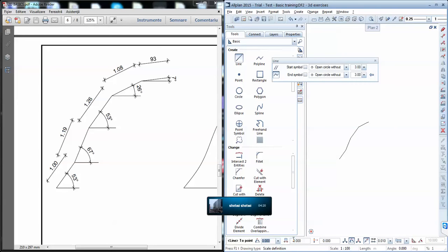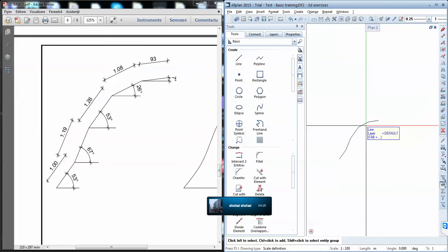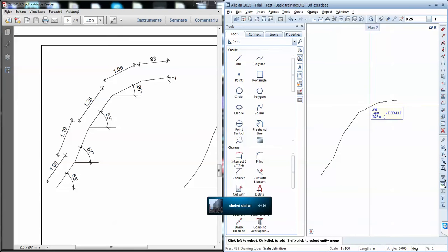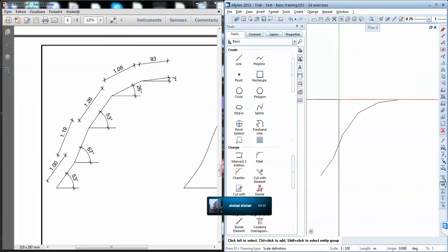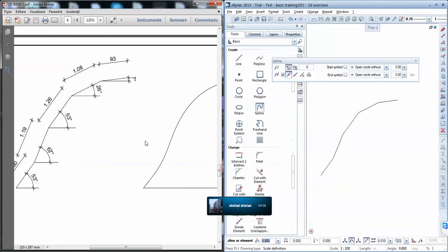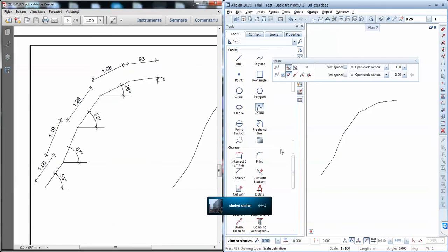And now the last 7 degrees and 0.93. This is the shape made using lines, so it has a lot of corners, it's not smooth. I'll then use the function spline, which will do a better approximation and will help me obtain this kind of shape, a curvy shape. I could have entered these points from the beginning to enter the spline with a polar coordinate system, but I wanted to show you how we can use it online.